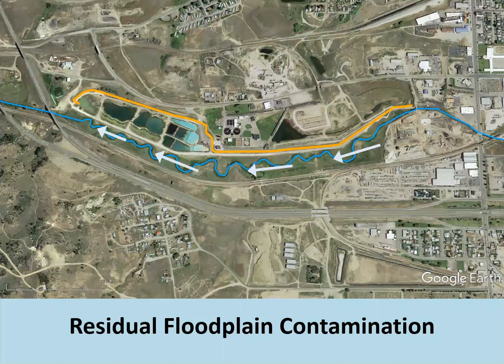But what they've done when they rebuilt this floodplain from here up to about here is they elevated the floodplain. So they engineered a distance between the aquifer and the stream. So now the stream is perched above the aquifer. So we're going to look at how well that worked too.